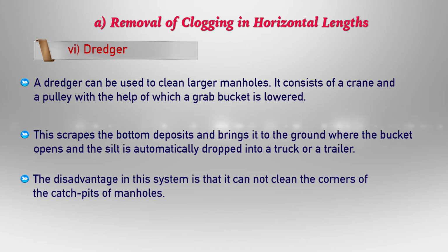The disadvantage in this system is that it cannot clean the corners of the catch pits of a manhole. Sometimes the deposits at the corners may become so hard that the same may be required to be chiseled out. You have to cut it using the chisel. It may become so hard.